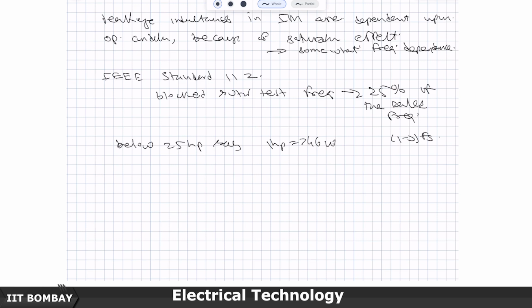Then you can just connect rated voltage and do your test, because you connect a rated voltage, the proper starting current or whatever is the condition according to the starter that you are using. Whatever are the starting conditions, fix that voltage line to neutral according to that, and then do your measurements.